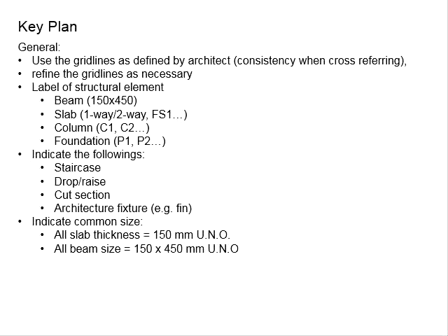You're going to polish your key plan, make it more stabilized and optimized, minimize the possible errors, always check against the architectural drawing, ensure there are no contradictions. You may also try to superimpose the architectural drawing onto your key plan to see if there is anything that you overlooked, any misalignment between your key plan and the floor plan, as well as to cross-check the view, make sure there are no clashes with the windows or the doors, and also cross-check with the cross-sections of the building.